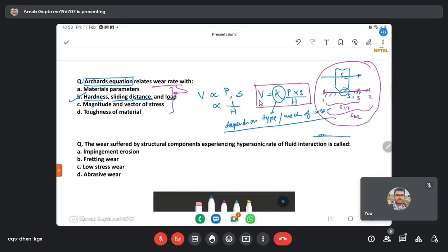As a result, your answer is also correct that the contact time is higher. So the wear debris is abrading the surface as well as the slider for a longer period of time or larger distance. While in 1-3 it's for a smaller distance and smaller period of time, as you may say.